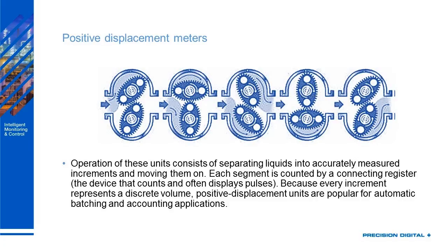What you see here is a positive displacement meter. And I could give an entire webinar on the functions of each individual type of flow meter, but that's not what we're here for today. Mostly what I wanted to point out was how these operate in terms of generating pulses. So in this example, a certain amount of liquid is going to enter this oval gear system.